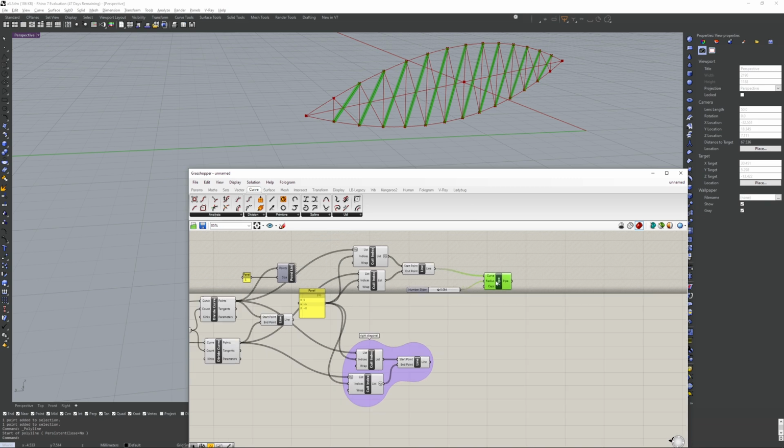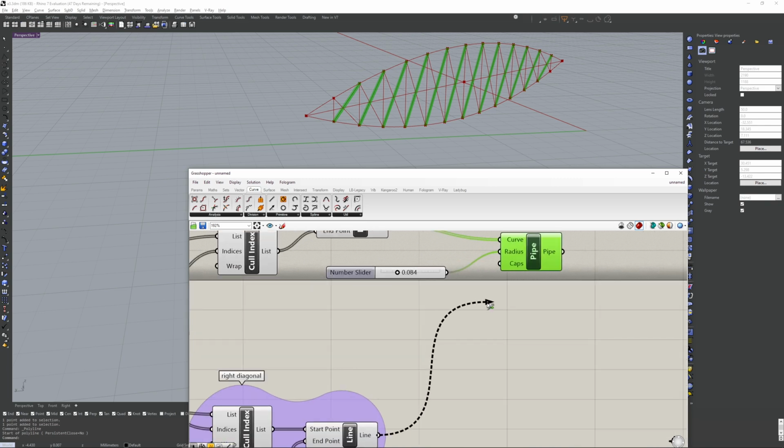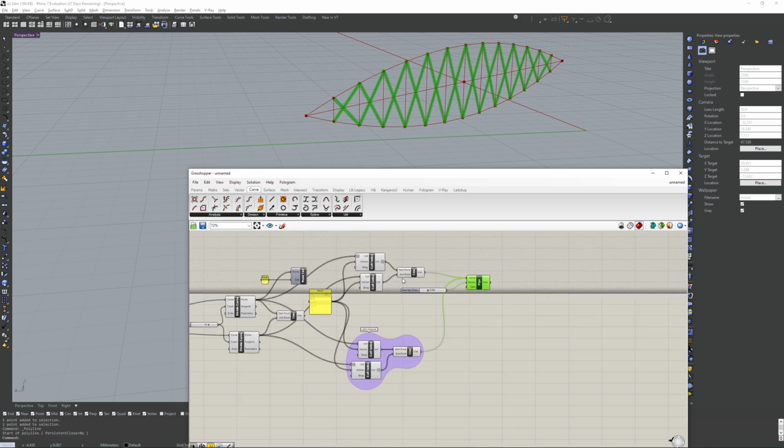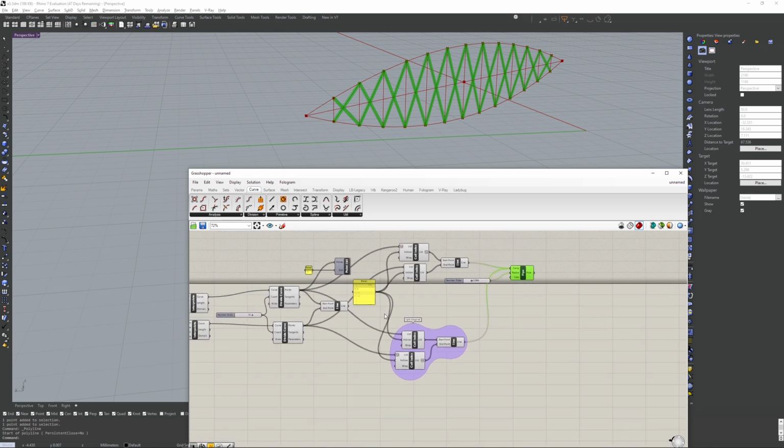So to add more curves to the pipe, you can drag and drop, but what you'll see if you just drag and drop it into here is it'll disconnect the other ones. Similarly, everything else that was connected to it, it'll disconnect. To keep the connections that were there previously, you have to hold shift, and you can see on your cursor it's a little green plus icon. When you hold it and you go like that, now you can add on to your input.